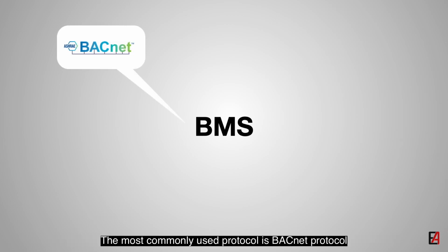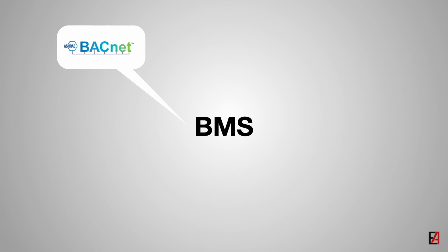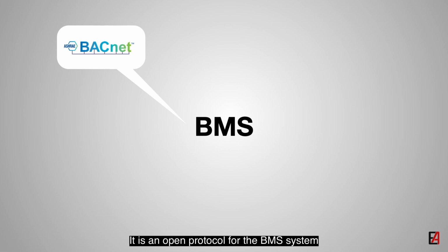The most commonly used protocol is BACnet protocol. It is a building automation control network protocol developed and managed by ASHRAE. It is an open protocol for the BMS system, so different BMS systems can be integrated.